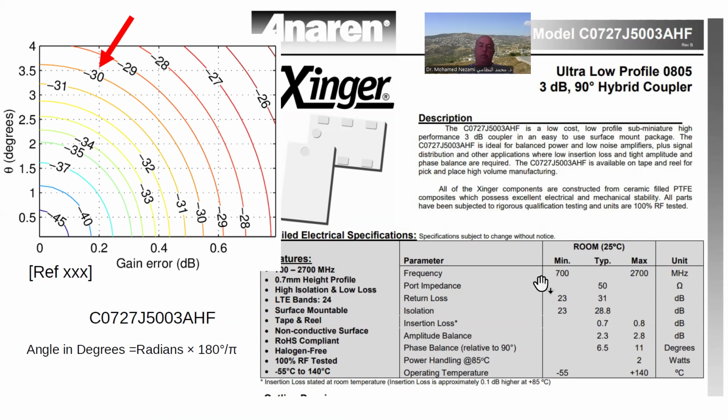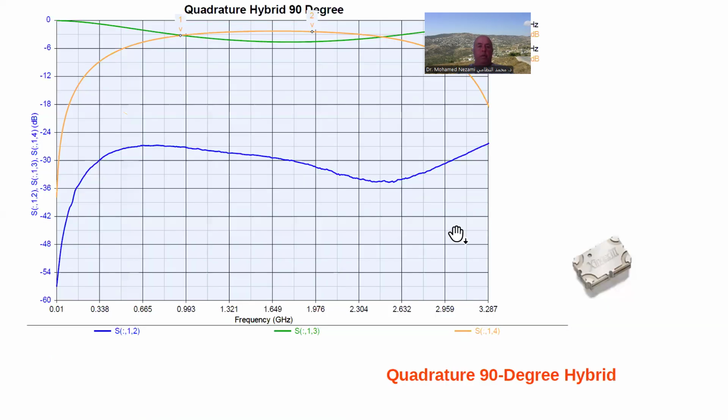Of course, I'm not operating in these bands here. I'm operating a little bit more than that. But this really puts you out on the quadrature gain errors and phase errors. They put you out somewhere in the mid-20s of image rejection. Which is okay, because in my case, I'm using an image rejection filter ahead of that.